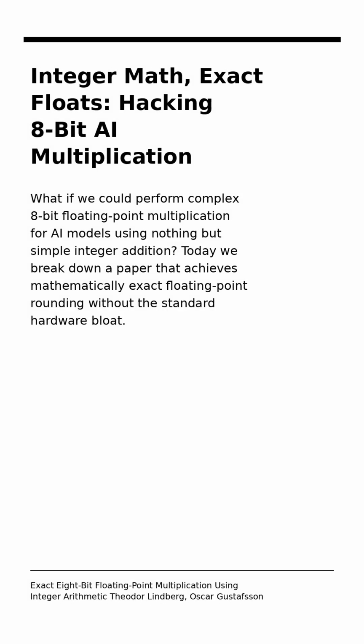What if we could perform complex 8-bit floating point multiplication for AI models using nothing but simple integer addition? Today, we break down a paper that achieves mathematically exact rounding without the standard hardware bloat. The researchers demonstrate how operating in the logarithmic domain allows formats like E5M2 and E4M3 to be multiplied efficiently. In this series, we will explore their clever error correction logic and see how this radically shrinks silicon area.